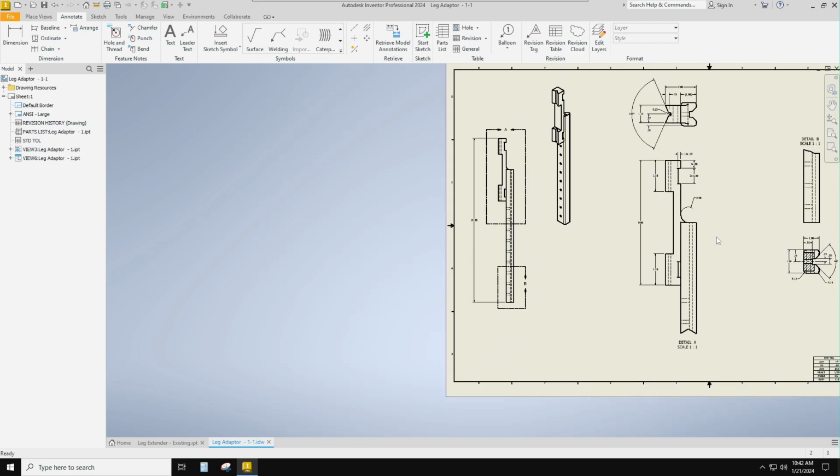So that's the gist of it. Remember, I need to always do dimensions to real surfaces. I showed how to do a breakout here. It's not really needed. I probably could have done better by putting a section through here versus showing this view that's a projection.